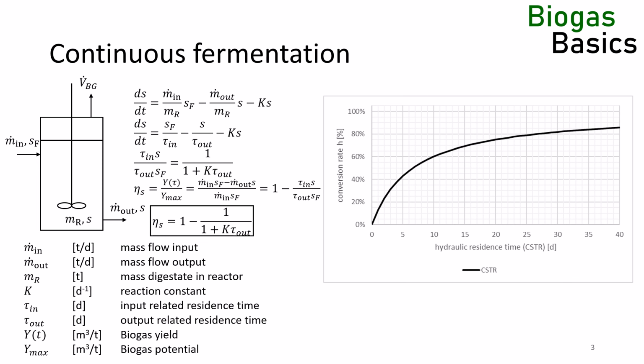It should also be large enough to convert the bulk of the substrate into biogas. I typically aim for an 80 to 85% conversion factor in the first reactor, not because of microbial growth reasons, but for viscosity reasons, to ensure that a large percentage of the degradable organic dry matter or substrate has been converted into biogas and only a residual amount of undigested substrate and the inert dry matter is left in the digester and requires mixing. More on this in the mass balance presentation series.